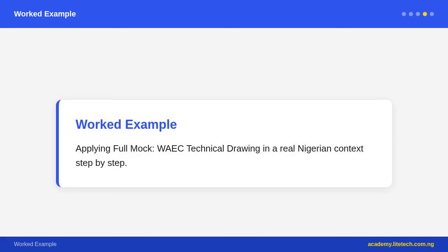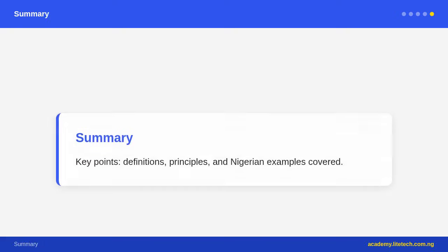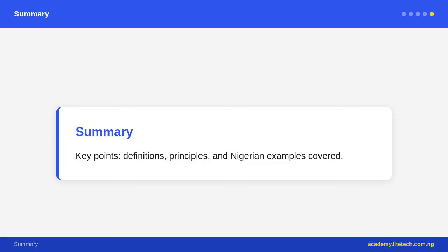Bearing designation: standardized numbers identify bearing type, size, and bore diameter. Conventional bearing representation. In a cross-section view, a ball bearing is represented by its inner race, outer race, and a cross X symbol indicating the balls. This is quicker than drawing each ball.